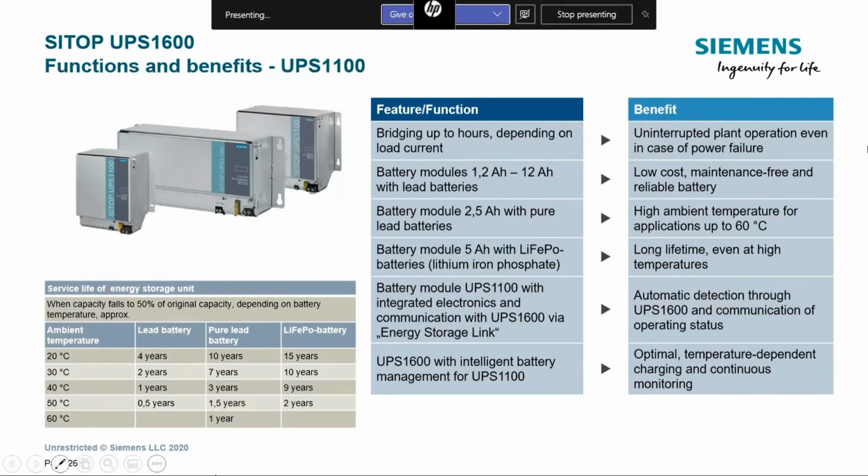And you can see, according to the table here, the lead acid batteries that we have, based on the temperature. Usually you are between 20 and 30 if it is a regular installation inside an air-conditioned area. But just a point to highlight here: when we say temperature, this is not the maximum temperature. So I know temperature might get maybe to 30 or 40, but this is the average temperature over the year.